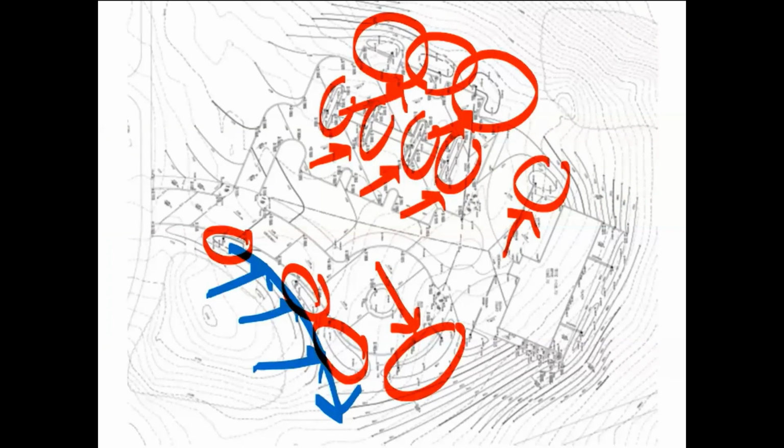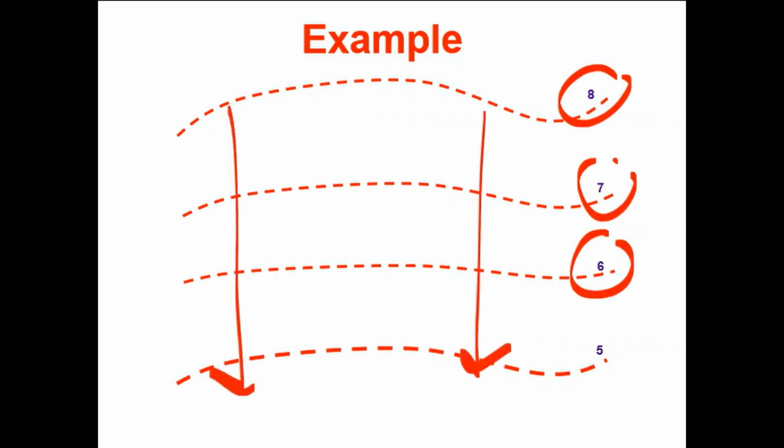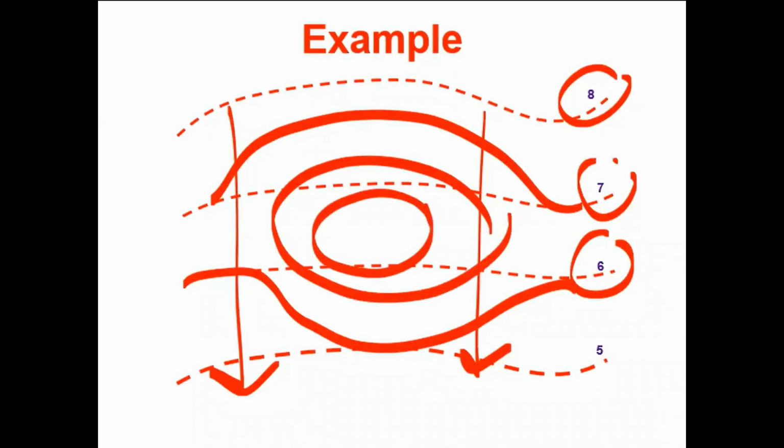But we're going to go through all of these so you can understand these as you start to grade your plans. So we're going to start with a very simple example of grading a bioretention system. Here we have a plan that shows the existing contours. We know that the slope is going downhill. We don't know the percent slope, but we can assume it's about 2%. And what we're going to do is talk about how we're going to then come in and modify this plan so that we can create basically a hole in the ground that will hold water.